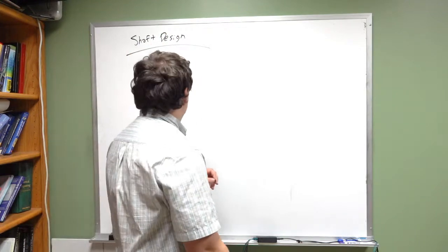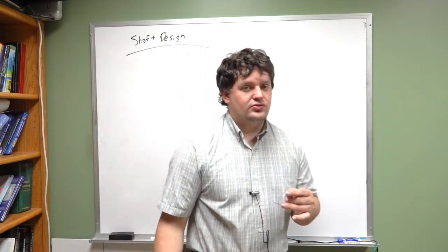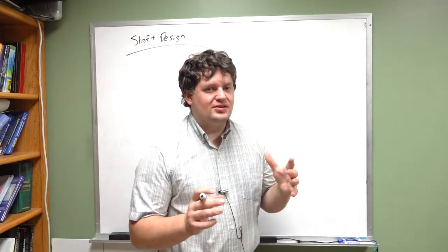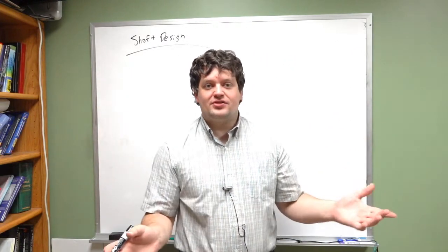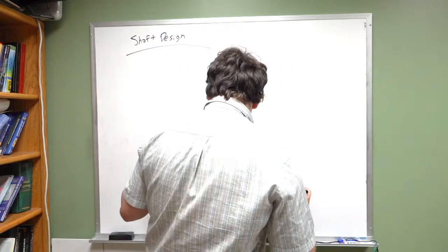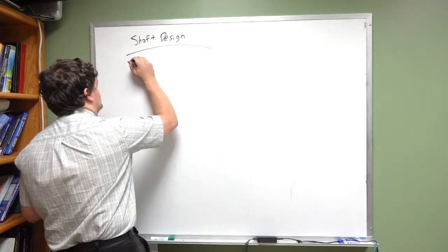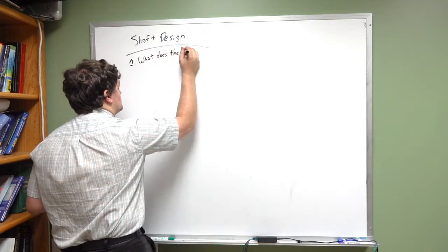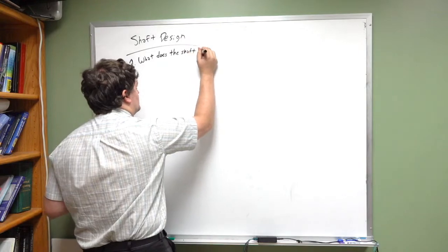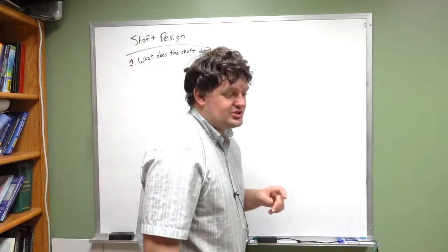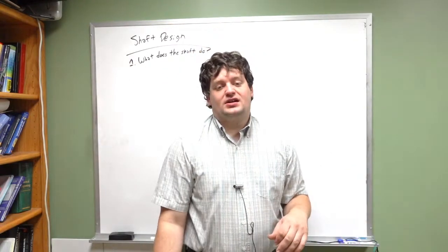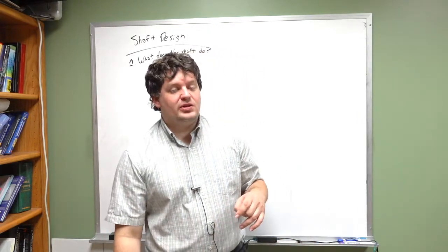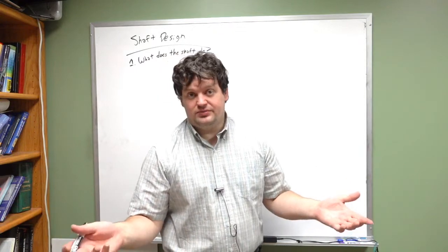With shaft design, we have a number of conditions that we have to take care of. So in order to design a shaft, the very first step you need to know is, what does the shaft do? If it's transmitting torque, which it usually is, then the shaft that we're going to end up designing is probably going to have to be pretty beefy.